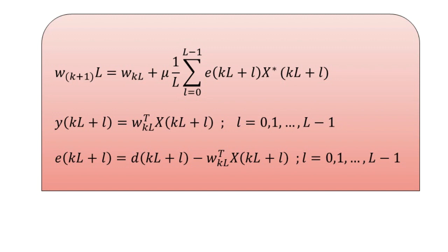For reducing the complexity of the LMS algorithm, there is also another approach. With the help of this approach, the LMS algorithms are also known by the name sign algorithms. Basically in these algorithms, the LMS coefficient update equation is modified by application of the sign operator to either the error signal e of n, or the data signal x of n, the input, or both of these, the error signal and the data signal.